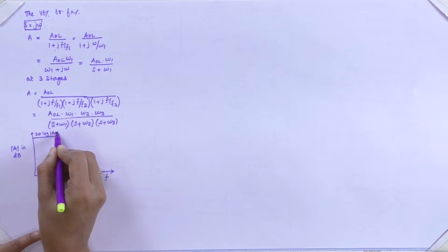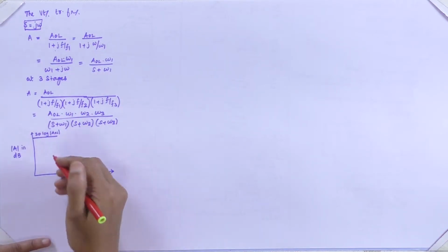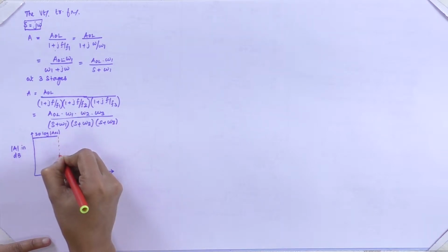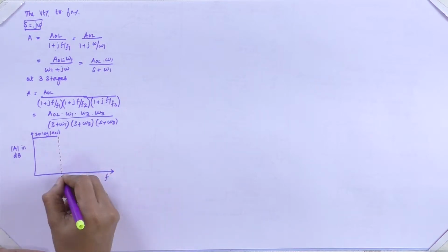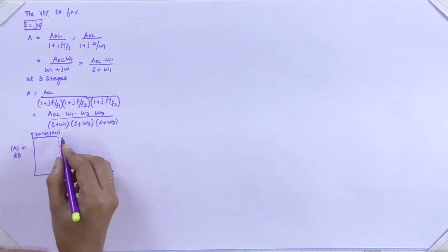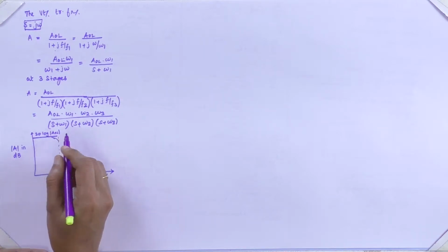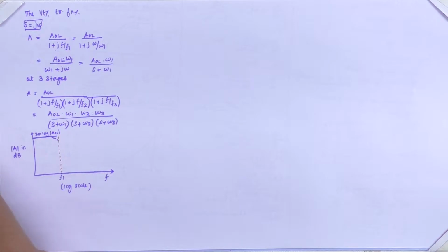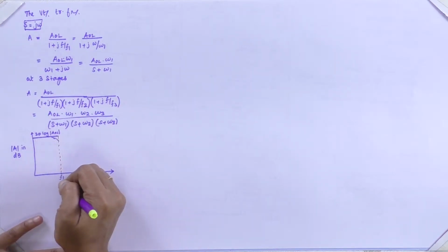That's the open loop gain, 20 log AOL. It will be drawn from this. It touches the corner frequency F1. By default, for an ideal, it will be like a straight one. For the practical case, it will be like a short curve with the difference between these two being 3 decibel. Okay. So from this it reaches a frequency F1.